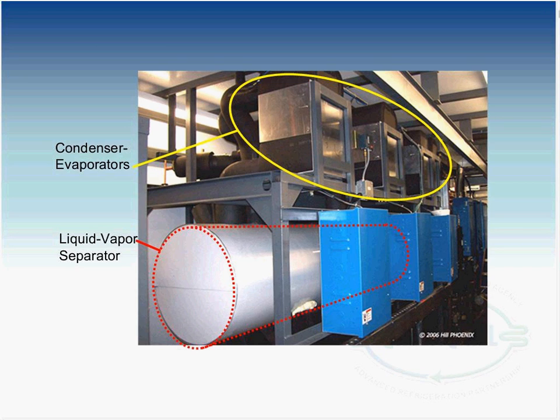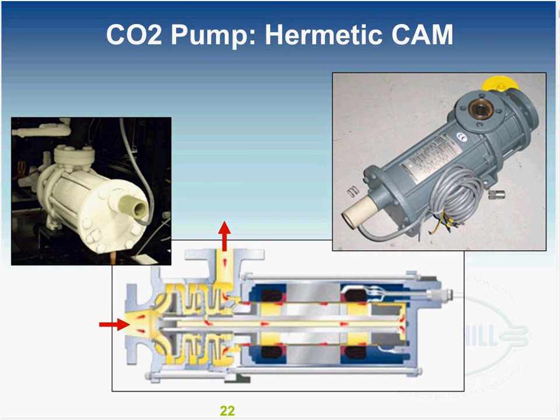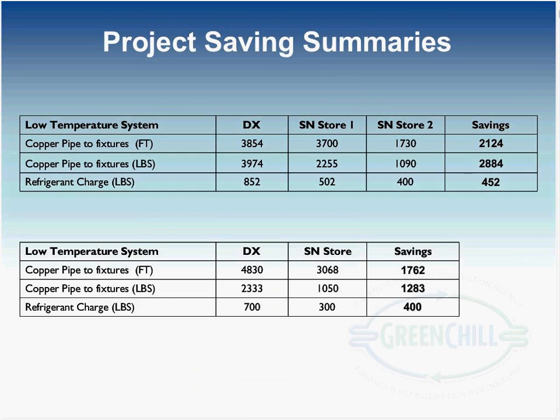And those evaporators are piped into the standard refrigeration rack. Out of the hermetic pump that's used to isolate the CO2. It's a very small pump. And of course, right there on the left is it insulated to show the frost there.